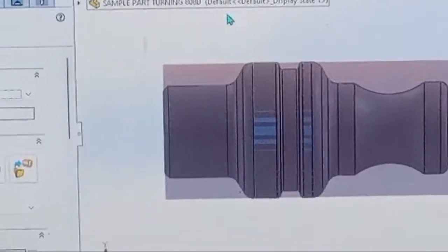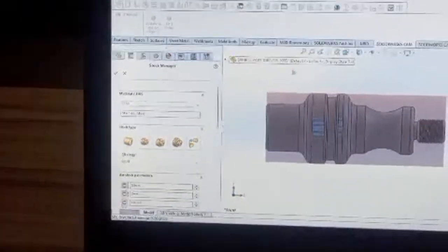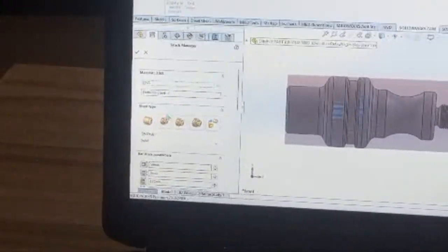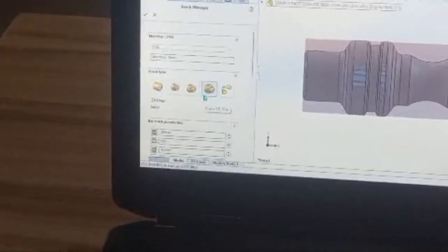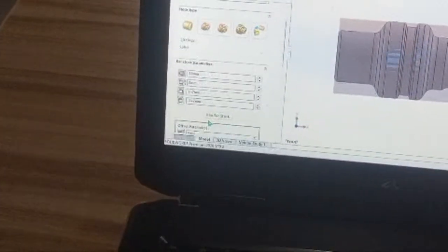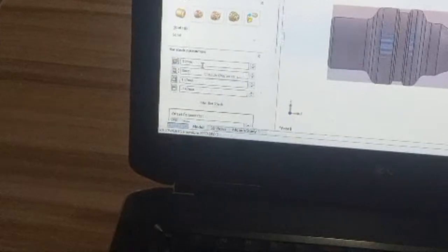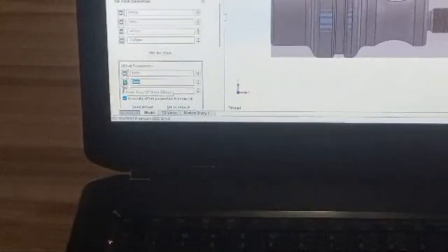And then you can go to somewhere here. We want to add our points. So basically it has detected that the stock is 59. That's the major diameter is 59 millimeter. The total length is 147. Positive, or total length negative 147. So it is up to you to give the offset. For example, this one on the positive side, I'm going to give a positive value.